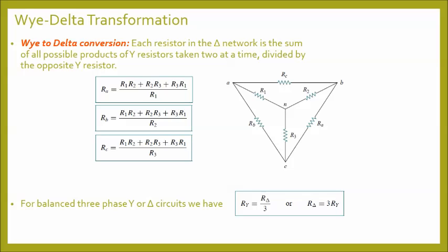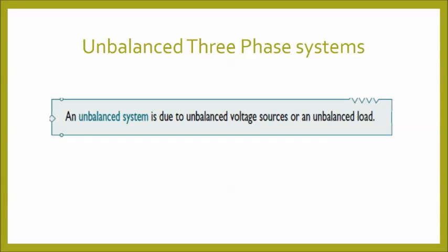Likewise, if I list down the steps of solving this type of question, they are as follows. Step 1: Identify the configuration on the source side and the load side separately. Step 2: Transform the load side configuration into the source side configuration using the given transformation method. Step 3: Draw the per-phase circuit diagram for any selected phase. Step 4: Build the mathematical relationships for the per-phase equivalent circuit. Step 5: Do the same for the rest. Take some time to read the following conclusions we have learned up to now.